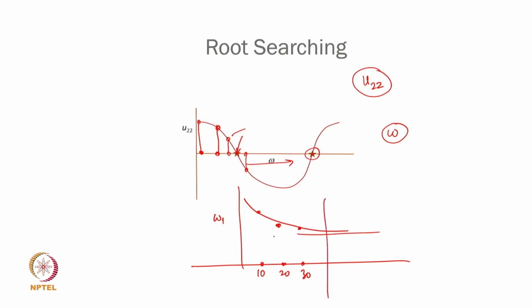So you then decide what your tolerance value is, what error you can tolerate for the first one. Typically people do it for the first 5 eigenvalues, depending again upon the rotational speed of your crankshaft, the shaft of the gearbox. What frequencies are you interested in? The highest of those should not have a large error just because you are discretizing into a smaller number of segments. Because the larger the number of segments, the computation increases.